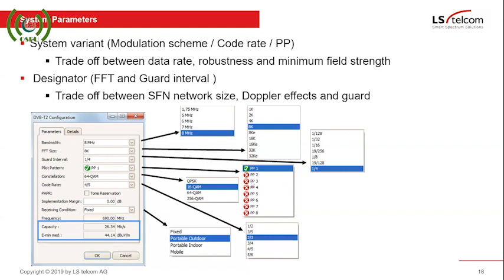Then you will see that with the pilot pattern, depending on the configuration that you choose, only certain pilot patterns will be acceptable for the receiver, because the others are disqualified because the system will not work with certain combinations of transmit configurations. Then again, you can look at your modulation. You can go for QPSK, 16-QAM, 64-QAM, 256-QAM. And you will also see when we get to ATSC 3, yes, you've got higher QAMs that you can use there.